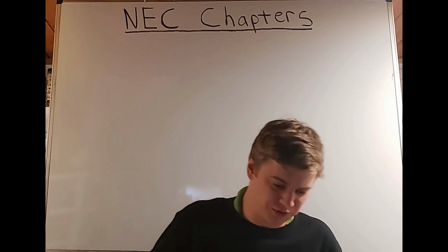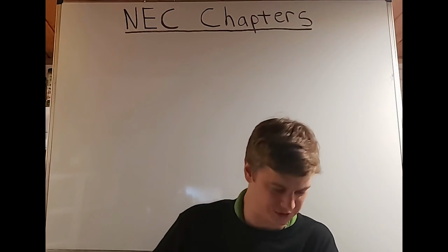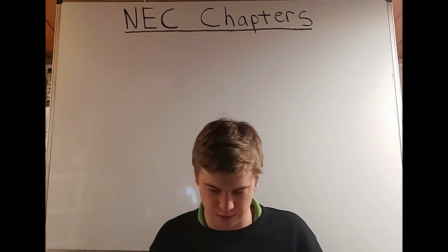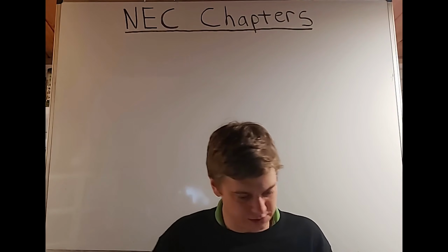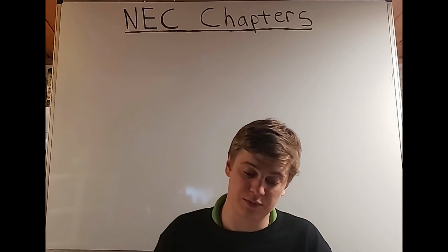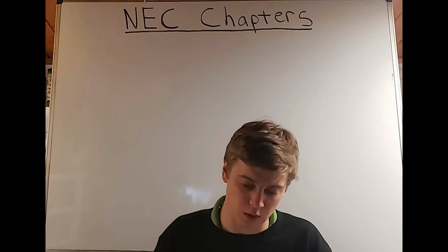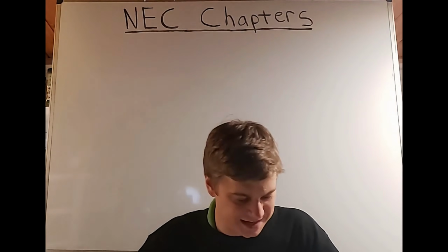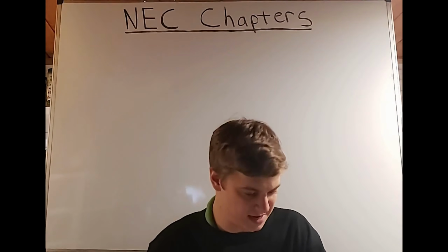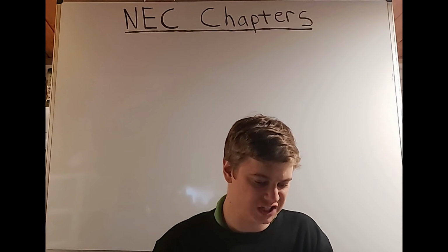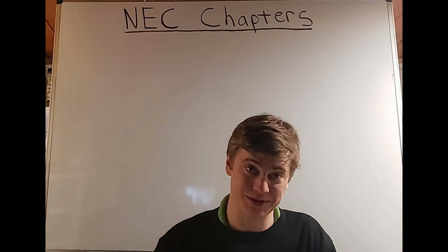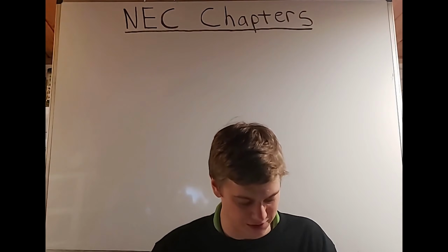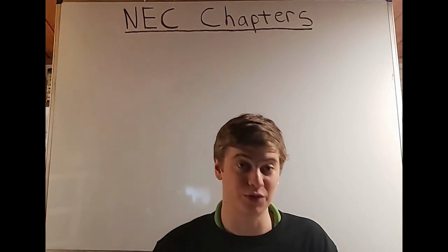Okay, and now Chapter 4, equipment for general use. We see the Table 400.4, flexible cords and flexible cables. That's an important one. Okay, so familiarize yourself with that. That goes along with Table 400.5(A)(1). And then we have 400.5(A)(2), the ampacity of cables SC, SCE, SCT, PPE, G, GC, and W. Table 400.5(A)(3), the adjustment factor for more than 3 current-carrying conductors in a flexible cord or flexible cable.